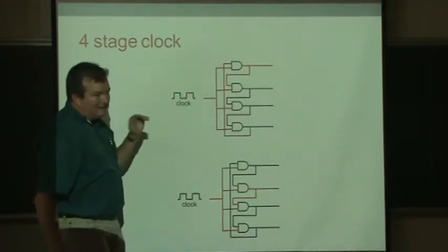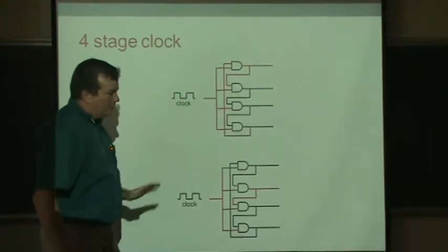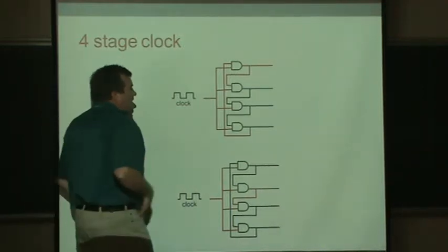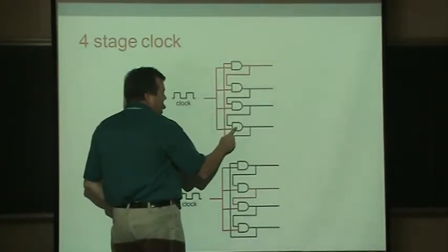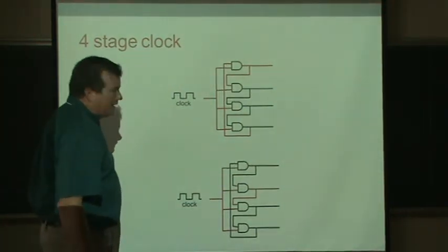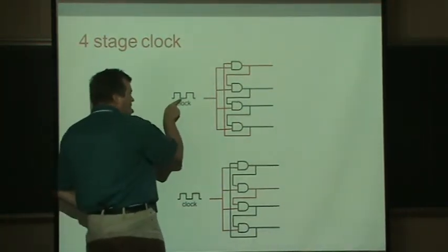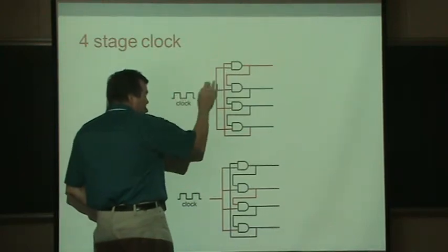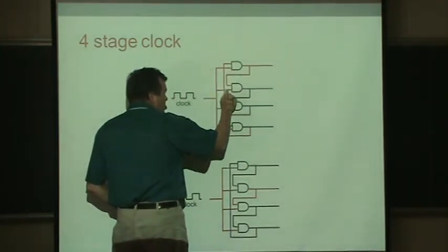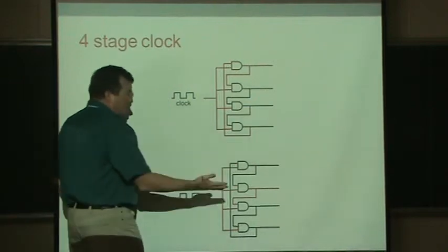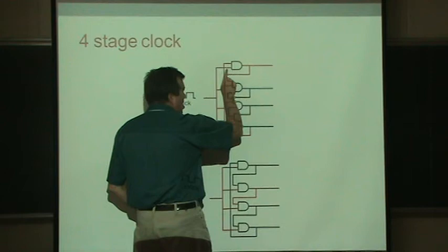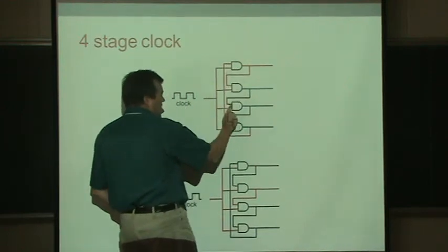This gets across the idea, but we would want to use better, safer equipment than this. If we have 4 AND gates put together, and the input is the clock signal, then when the clock signal is high, the lower inputs of all 4 of these AND gates are turned on. So then what would their outputs be? Their outputs would be whatever the high end was.